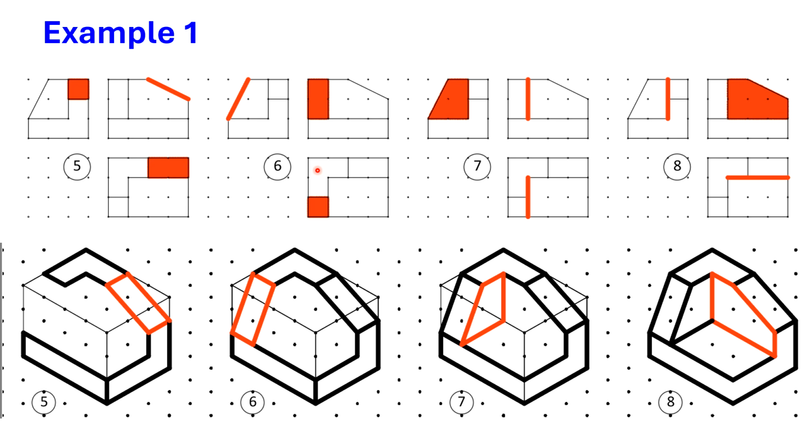Then if you go to the sixth one, there is another inclined line in the side view, that means there is another inclined surface. So this is exactly coinciding with this surface, and in the top view this is coinciding with this surface. So by combining these three views in the 3D object, it is actually coinciding over here. So join these two points, and again join these two points like here. So you will get another new surface over here.